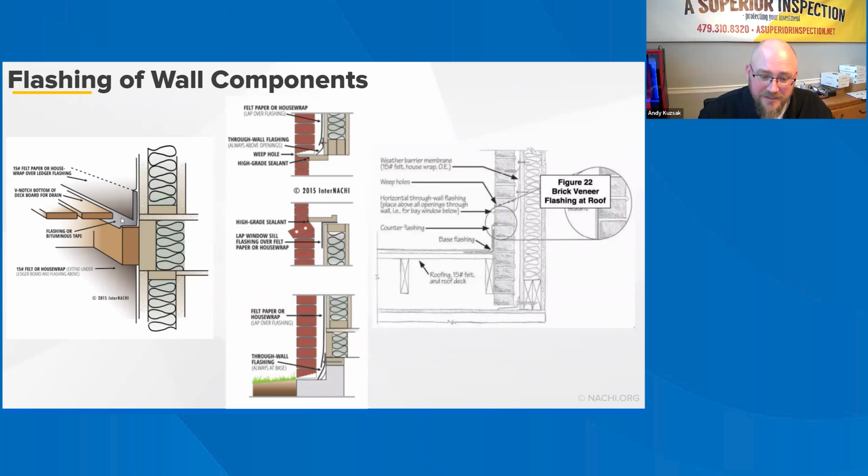So oftentimes, because a lot of people are moving to my area, builders are basically able to say whatever they want because homes are in short demand, especially new construction. And so oftentimes when I call out the missing deck ledger flashing, the builder will refuse to do anything about it, and the homeowner is left having to have that applied or reinstalled. So just stick to your guns, call it out, make sure that you're protecting your clients as best you can, and let them handle it from there.